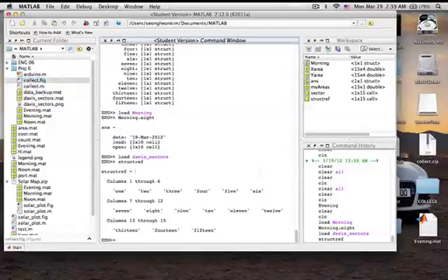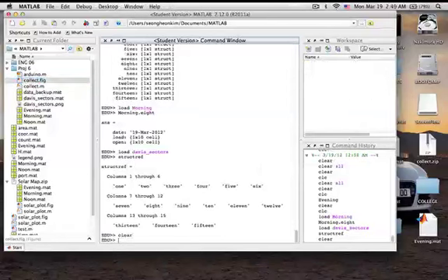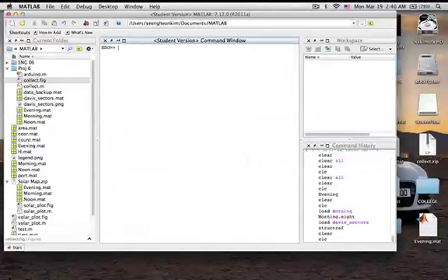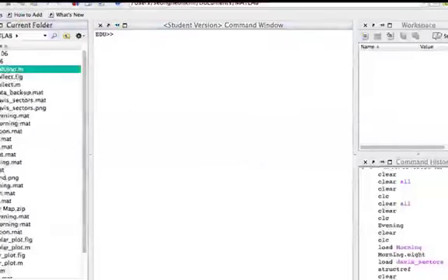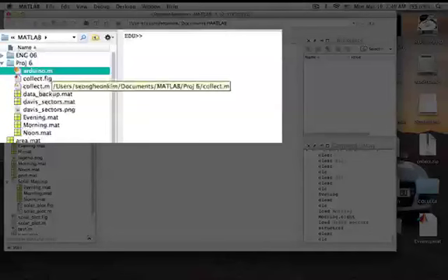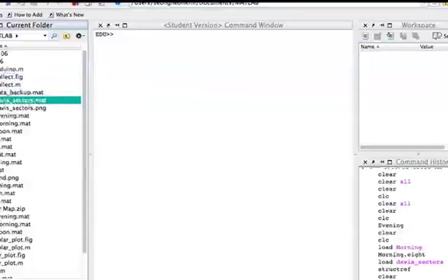I'll take you to the first part of our GUI, which is gathering the data and measuring the voltage from the sunlight hitting our solar cell. So first, make sure you have the Arduino M file in the same folder you're running the whole thing, because the file calls up the Arduino object, and without it you can't run it. We also have some additional data sets here. These 3 are for storing the data that we collect. This is for the GUI internally to run.